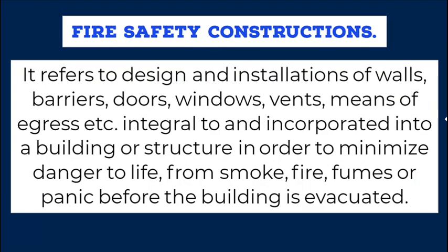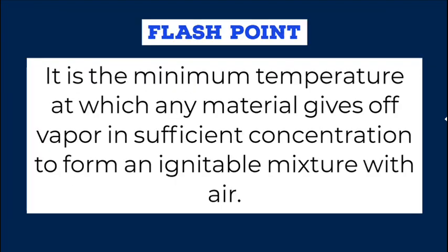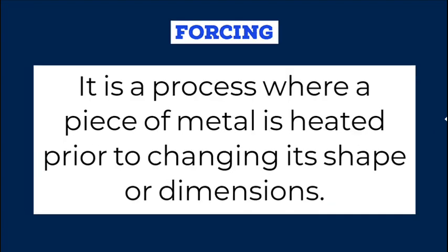Fire safety constructions. It refers to design and installations of walls, barriers, doors, windows, vents, means of egress, etc. integral to and incorporated into a building or structure in order to minimize danger to life from smoke, fire, fumes or panic before the building is evacuated. Flash point. It is the minimum temperature at which any material gives off vapor in sufficient concentration to form an ignitable mixture with air.